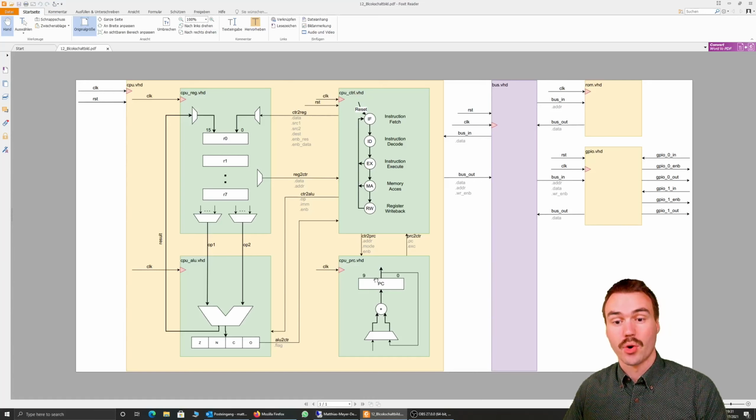It depends what the program counter value is. Here we only have a ROM, so this program counter will always point to the ROM model. And then, as we have seen the last time, one clock cycle later we receive the data which is stored inside this ROM model.